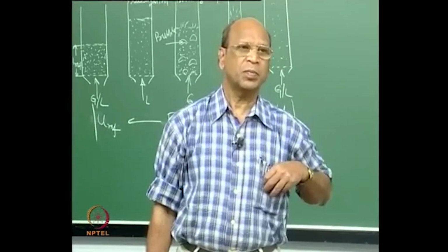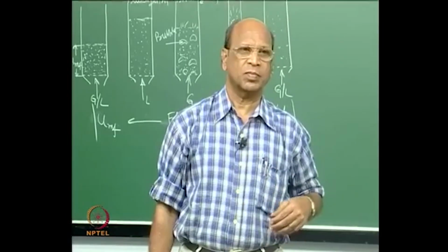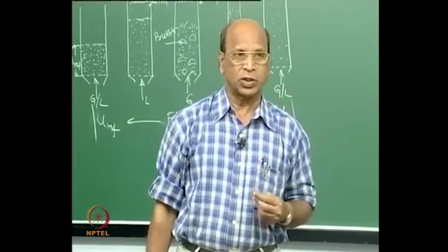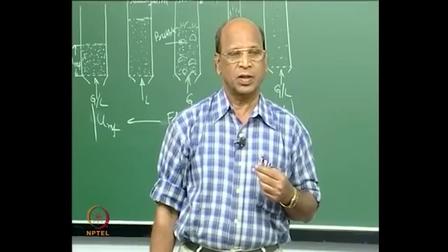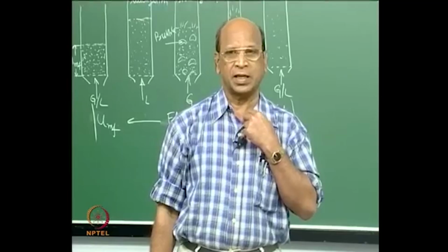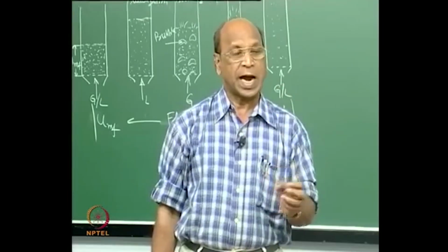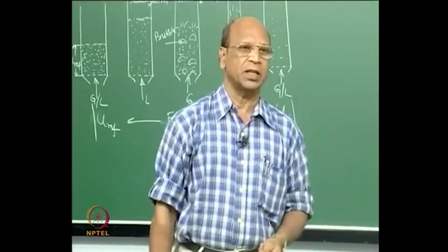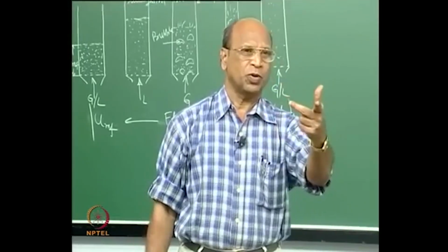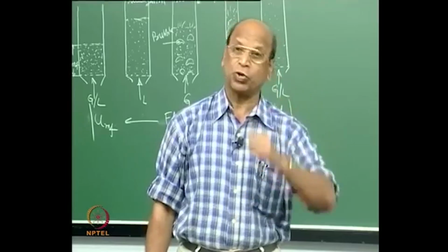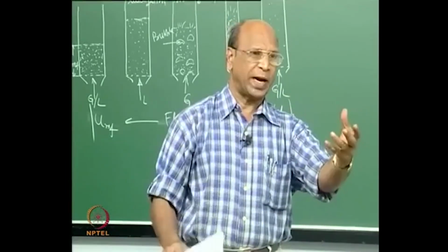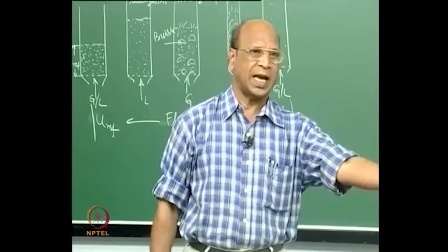But the particles have to be the same particles. You can't use different particles. That may affect the efficiency of fluidization. Sometimes it will help also, it seems. To get smooth fluidization, they take slightly coarse particles and add fine particles. Then it seems you will get better fluidization. So, this is always counterintuitive, and you get a kick when you have counterintuitive things. If what you imagine in your mind and what is happening are the same, there is no kick.